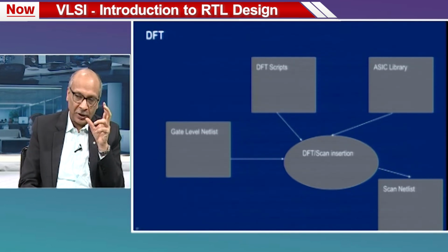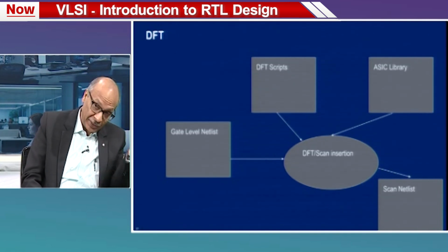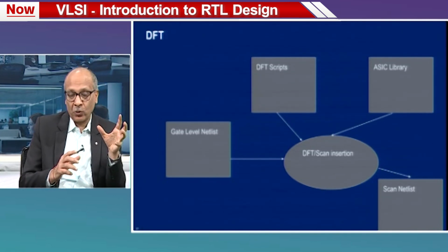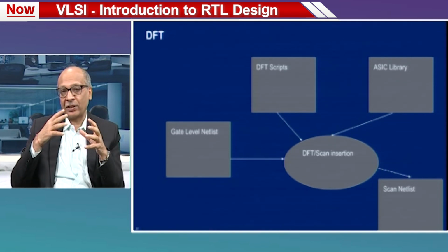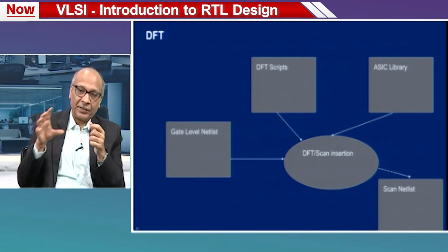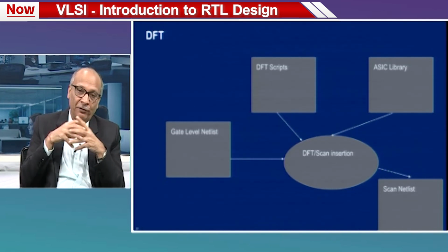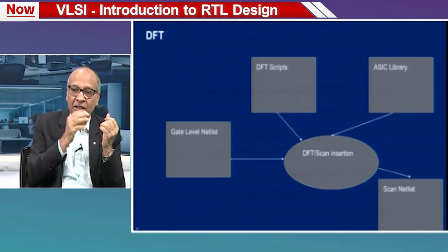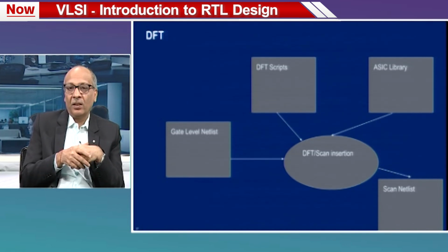So, this is what we were talking about slightly earlier, that when we are writing the RTL, it should be written in a manner so that the design lends itself easily to ATPG and scan insertion. If I have not written my RTL correctly, even if it is functionally correct but not easy for scan insertion, then my testing will become difficult, which means either more time on the tester equipment or defective chips going to the customers. So, I have to take care of these DFT aspects at the RTL stage itself. That is where tools like lint etc. can help.